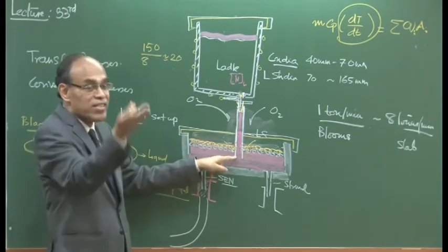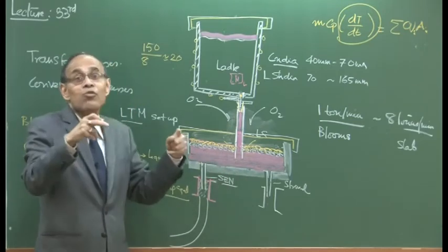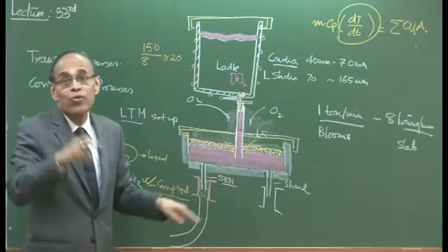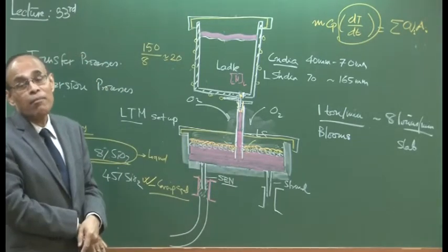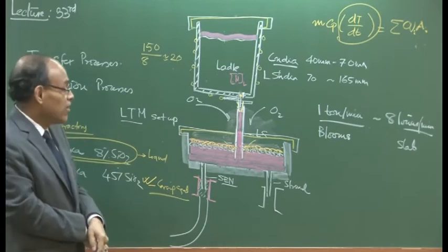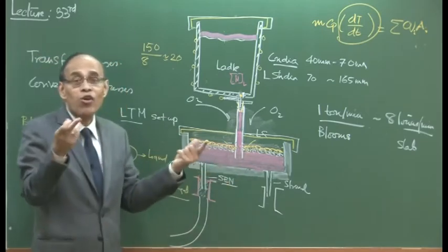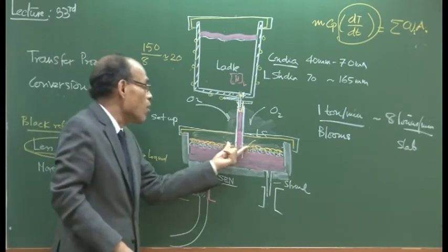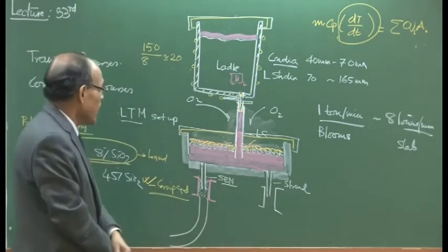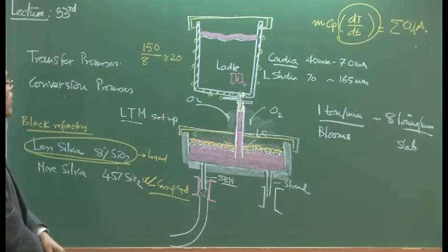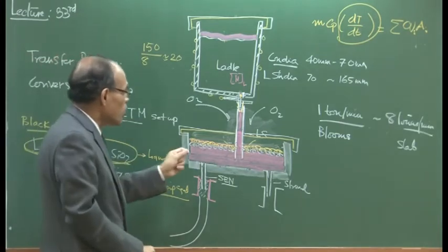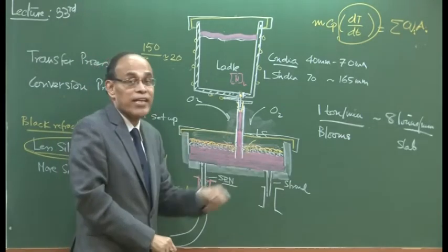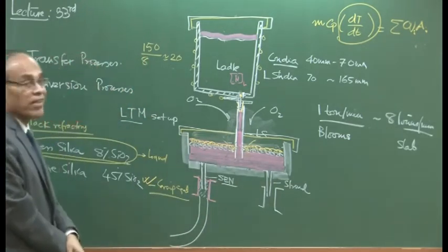even though the shroud tip is not submerged, it will take some time to get submerged, the molten metal discharged from the shroud will see an environment in the tundish which no more contains atmospheric oxygen, but contains an inert gas like argon, and thus reduces the extent of oxygen absorption and nitrogen absorption in the tundish. So, flushing of the tundish prior to the beginning of the casting is a very important exercise, and it is also important that the tundish is operated with a reasonably tight cover.